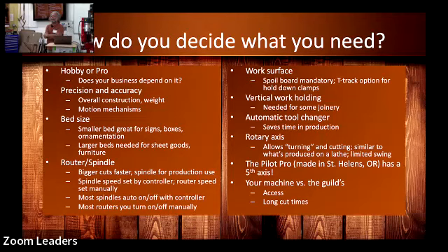One other consideration is the noise. The router is much louder. Yes, Tracy Ann highlights the fact that routers are considerably noisier than spindles when they're cutting. True that. And you're going to want to be around the machine when it's cutting. So noise is a factor. Dust collection is too. You'll have dust collection running when the machine is running as well.